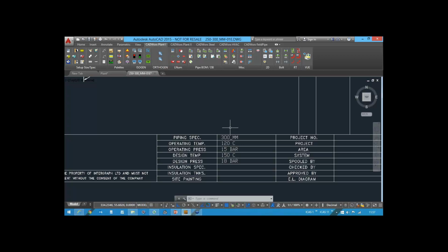I know most of you might have struggled much for this particular output, where you generate the isometric separately, and after that it's like a data entry work, opening each and every file and typing the inputs whatever is required, where even a 0 or 1 which is misplaced or added additionally causes a big loss. So in this case, we don't have to worry about entering data in the drawing, because you are going to give the input only in your notepad.